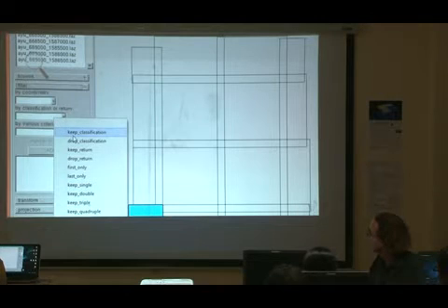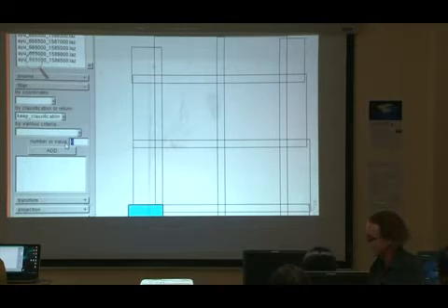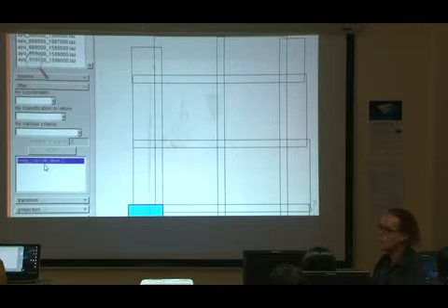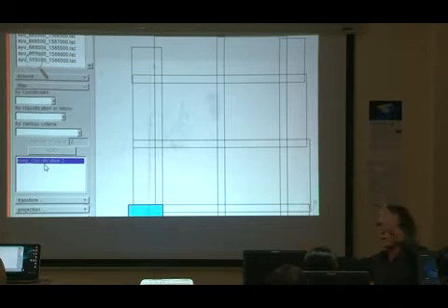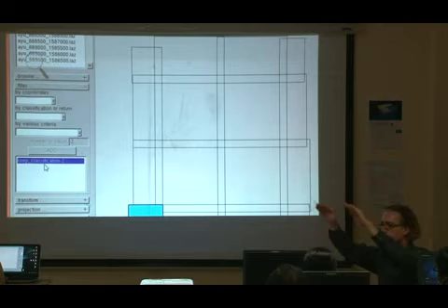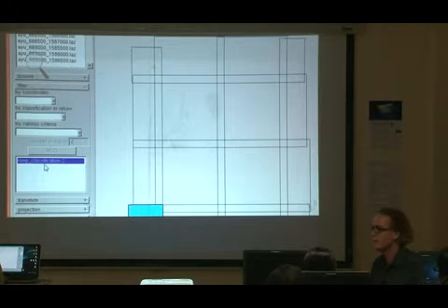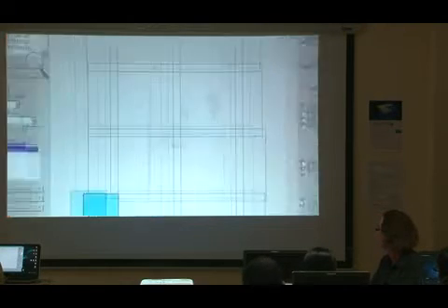But I still only want to use the ground points, because I want to make a DTM. So I want to only use the ground points for every tile, including the buffers. Make a big tin that's 30 meters bigger in all directions than the real tile, and then only raster the center 500 by 500 meters.